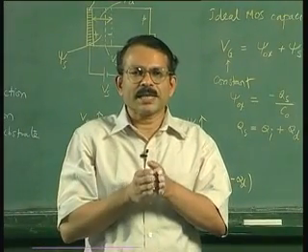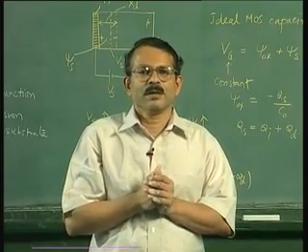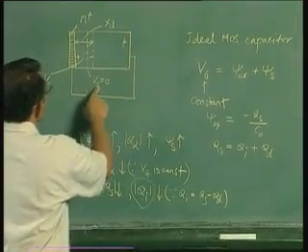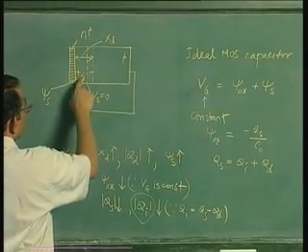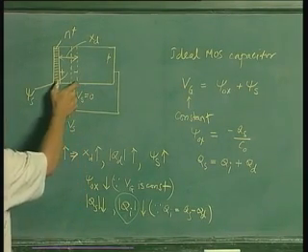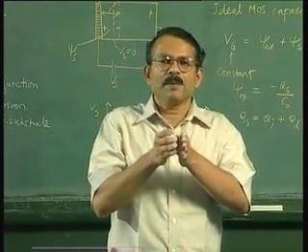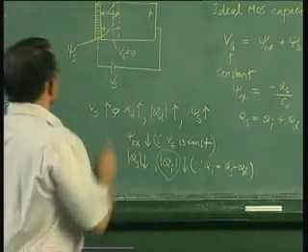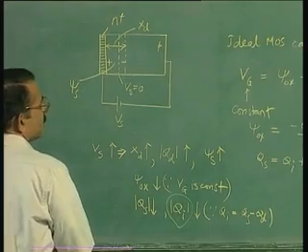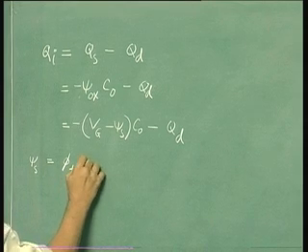So when an inversion layer is created, obviously there is a potential drop in silicon, otherwise you cannot create the inversion layer, and that potential drop is equal to phi t or twice phi f. So when Vs is equal to 0, psi s is twice phi f or phi t. So for any non-zero Vs reverse bias, your potential drop across the induced NP junction from the PN junction theory will be the built-in potential plus the reverse bias. Here the phi t is like the built-in potential for this n plus p junction. So we can write psi s is equal to phi t plus Vs.